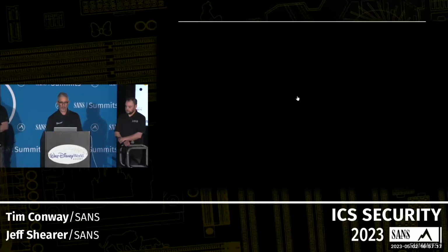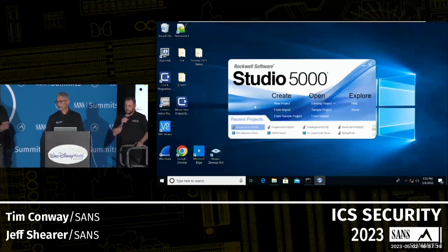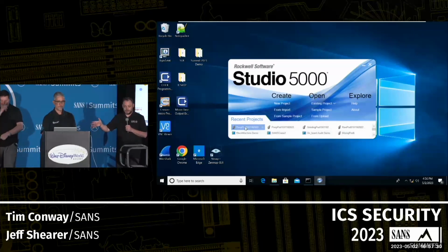is go back here. I will point out one element. The FactoryTalk admin had not been configured at this organization for security purposes. They didn't set a password on this. They tried to log into the application and it was password protected. They can't take a backup copy of a project file and launch it from their tool set. Their licensing is now locked. So they had to provide the project file to someone else, meaning you need to have a support agreement with your vendors or your system integrators who can be a partner in this fight with you.